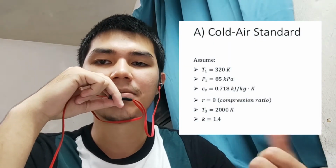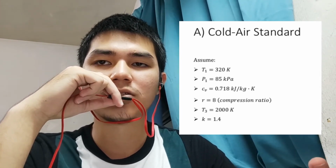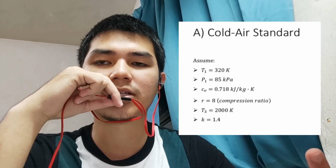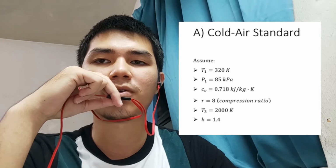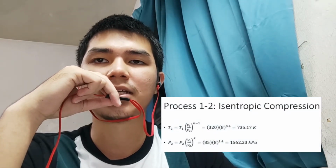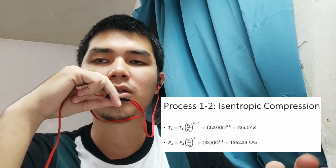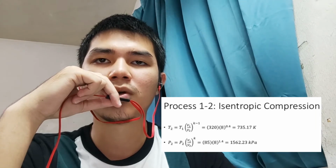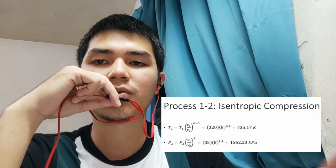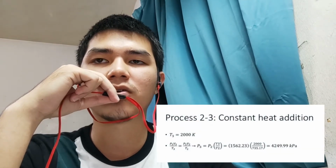The assumptions are temperature 1 is 320 Kelvin, pressure 1 is 85 kilopascal, compression ratio equal to 8, maximum temperature T3 is 2000 Kelvin, and last but not least k equal to 1.4, which is practically important in the cold air standard assumption. For process 1 to 2, the isentropic compression, we can use the formula r to the power of k minus 1 and r to the power of k to get temperature 2 and pressure 2, which are 735.17 Kelvin and 1562.23 kilopascal.